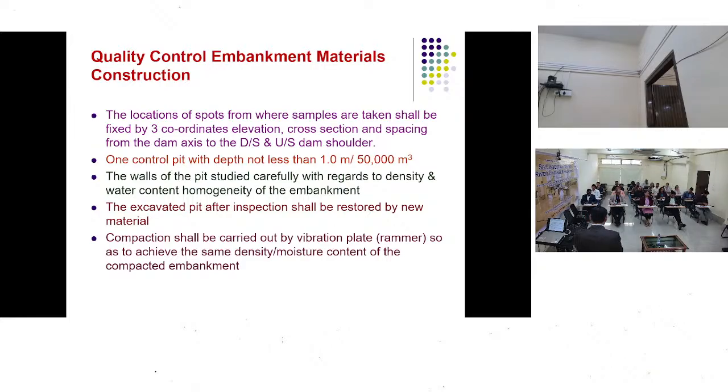So the best is you go in for a total station, and then we can plot it back in a 3D system finally, so as to understand, okay, have we been able to cover the whole system or not. So that is very much required to give confidence.